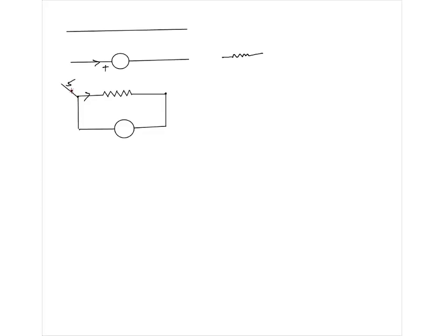But practically speaking, can a voltmeter work like magic? It takes no current and the coil rotates in a magnetic field. How can the coil inside the voltmeter rotate in a magnetic field if there is no current passing through it? The magnetic field applies force to current. If current is not flowing, how can there be any force? If there can be no force, how can there be torque? That means the voltmeter is going to eat some current. You just cannot help it. But you can minimize the damage.